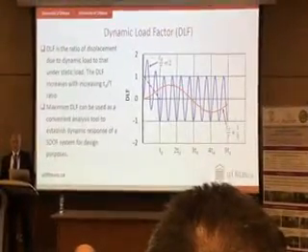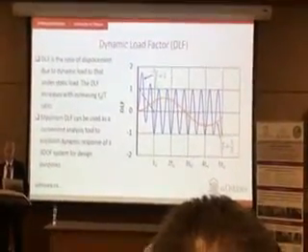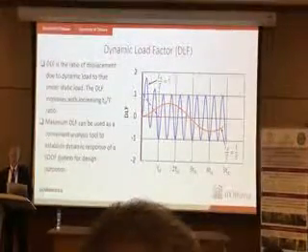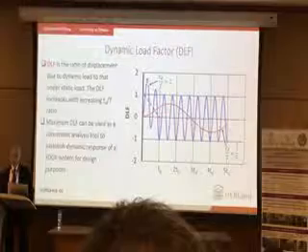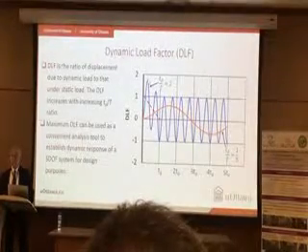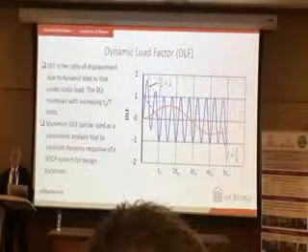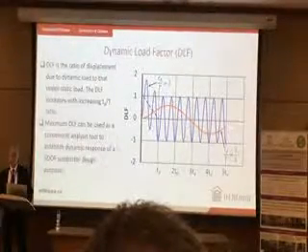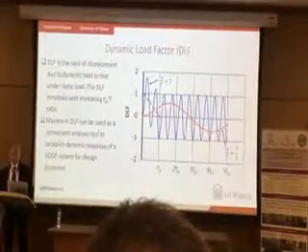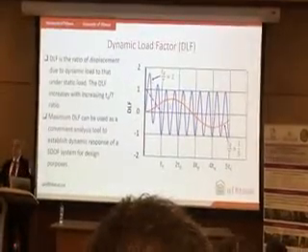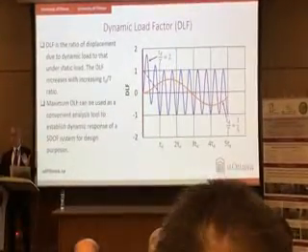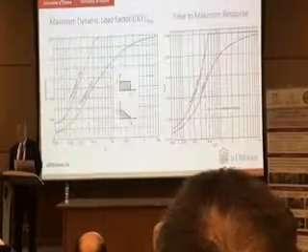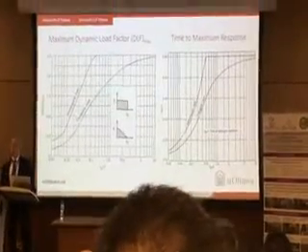As I said, the ratio of duration to building period matters. If it is high, in this case 2, you can see the ratio between dynamic to static is approaching 2. I said impact load, it is 2. And if the ratio is 0.2, 1/5, then it can be lower. So once again, period of excitation and period of the structural element correlate very well. So these are the design tools, right?